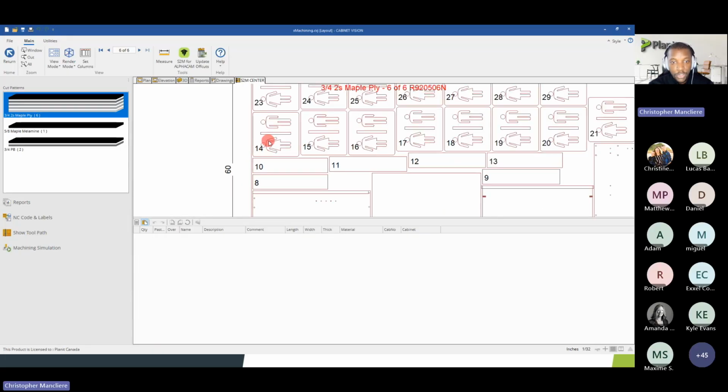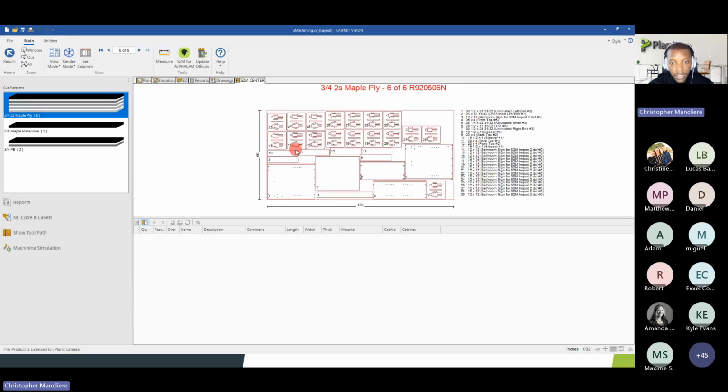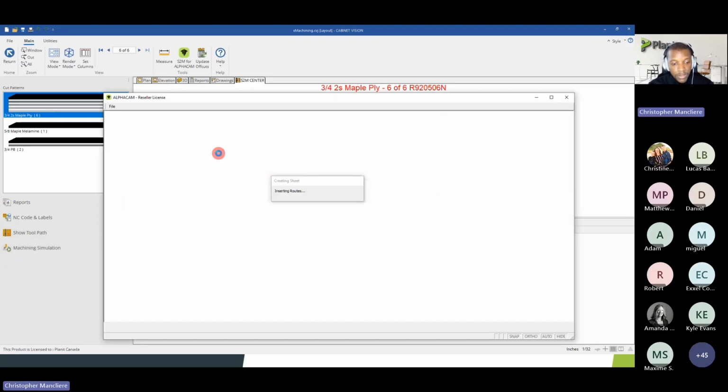And also it's allowing me to show you how the CAD import works. So if it's properly done, you'll see that what you have in your CAD file will be imported in your TM directly without having to redraw it in CAD. And we can run the simulation. So here it's inserting the machining. There's quite a few parts, so that's why it takes a bit longer. And by the way, the simulation is an add-on that could be added to your TM. This is something you can add if you want to run simulation directly from CAD without having to do it on the CNC machine computer.